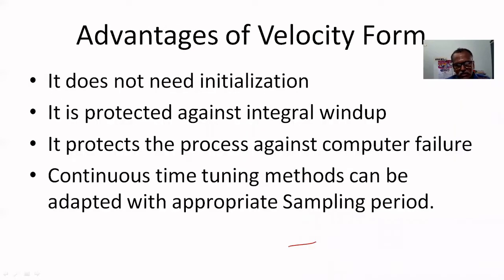Three advantages we'll see one by one. The first advantage is there is no integral wind up. What is integral wind up? Integral wind up is, if any persistent error is there, then the integrator will continuously integrate that error and the controller output will saturate at one point. If the error exists for a long time, the controller output will saturate because of integration.